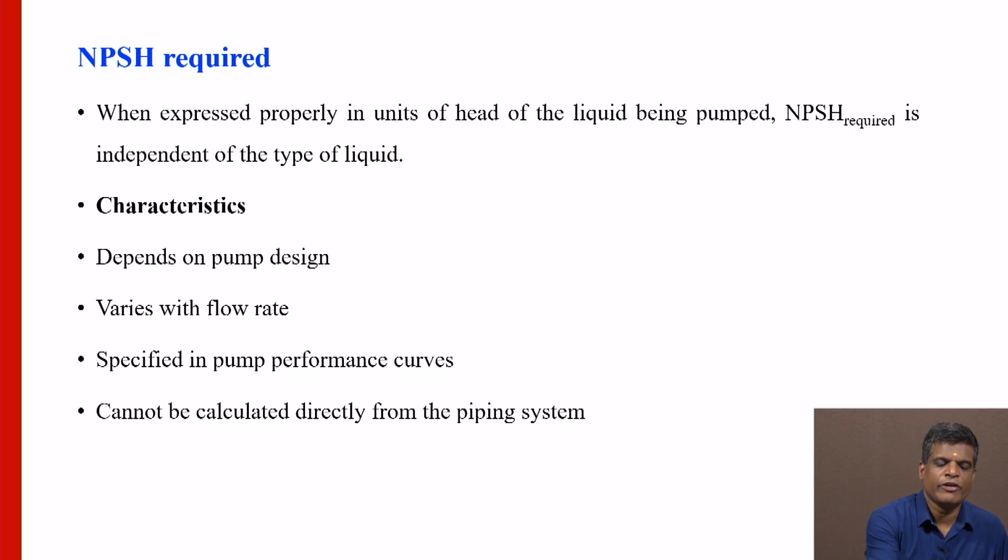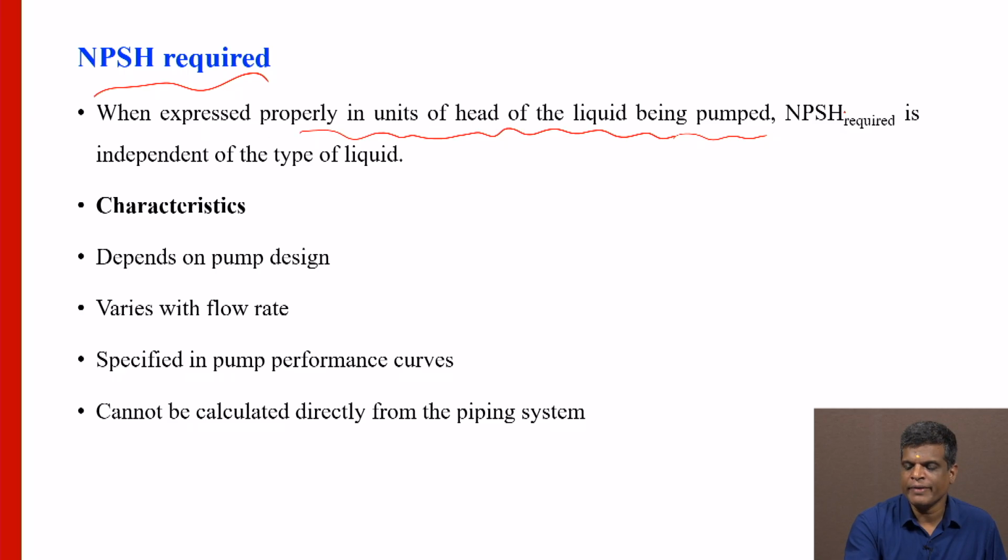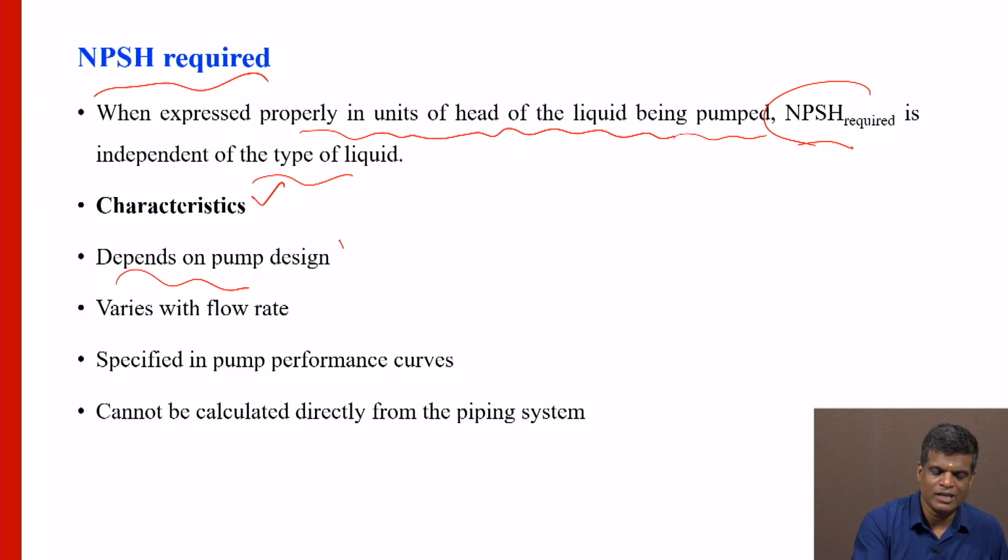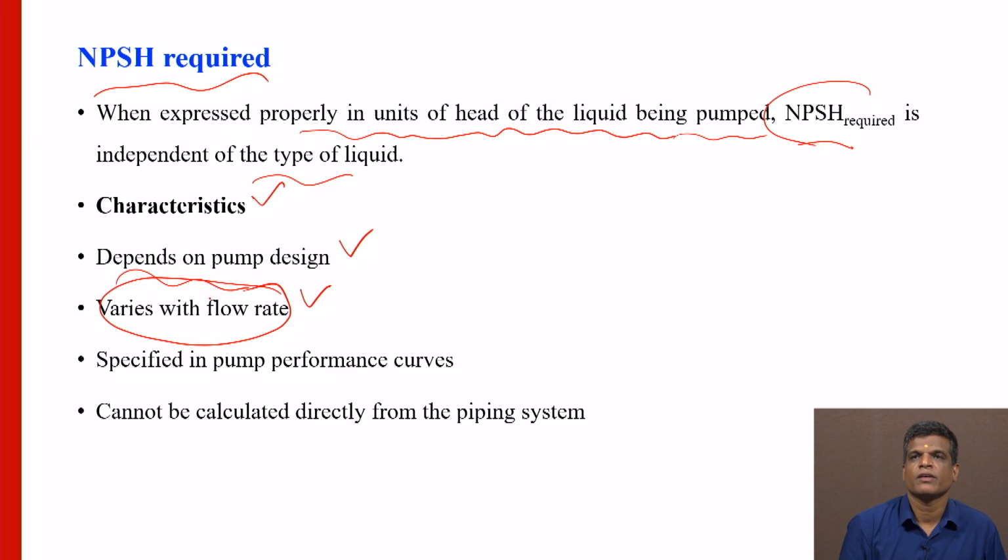So then NPSH required: when expressed properly in units of head of the liquid being pumped, NPSHR is independent of the type of fluid. What type of fluid you are using doesn't matter. So what are the characteristics here? It depends on the pump design, how you design the pump, which is very important. It varies with the flow rate.